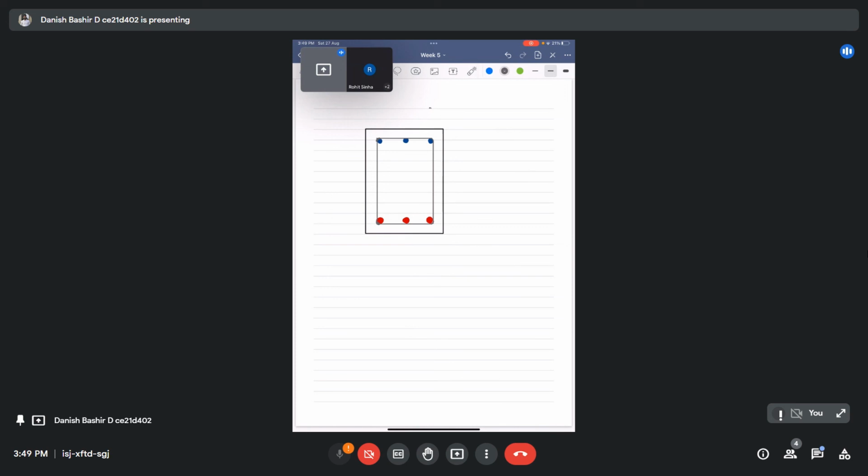Here we have to make the bends like these, 135 degrees. These are the details that you will study in detail in the classes. I have to make this 135 degrees. So this was our coming as 250 mm, and this was coming as 400 mm. Sorry, 348 mm.